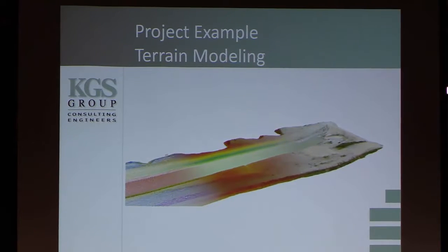So we were able to generate a digital elevation model from this, and then in turn that DEM was used for quantities. It was also used as a record of the as-built of the channel, and then it was used for hydraulic models to determine future performance of the channel, and also for condition assessment of the slopes of the channel excavation.